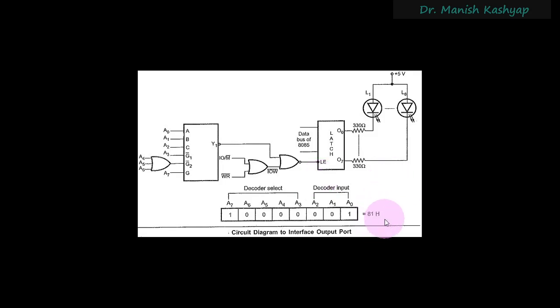This address can be any address of your choice. You can again see here that the circuitry is like this. This is an output device, and in this particular microprocessor, we have set LEDs. So you can see that Q0 to Q7, there will be 8 total outputs here, and these 8 outputs will be connected to 8 different LEDs.